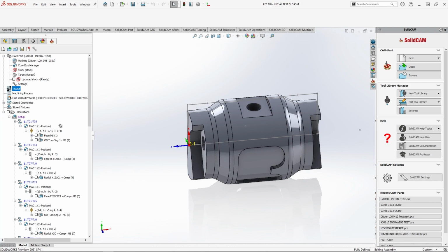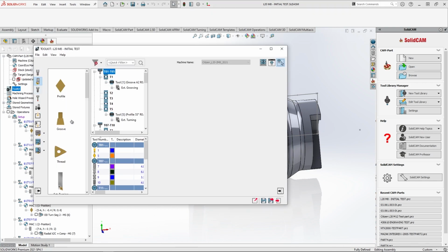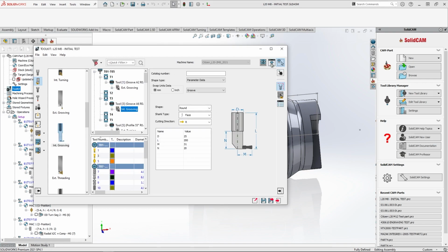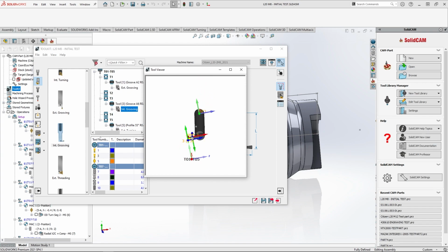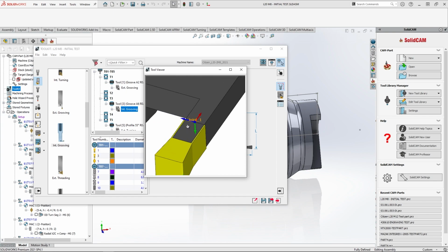I have over here a Swiss type machine, and I'll just take the tool itself, and as this is internal grooving, I'll double click or take it to any station position. I'll look at the coordinate system that we have. We have a coordinate system of our shank, and here we have the interesting part. The Z goes over here, the Y goes over here. That will be our insert. And here we have a joint.